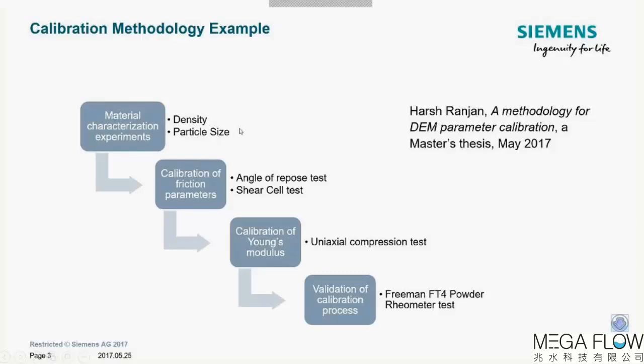We can then do some initial approximations, keeping in mind that we want to simulate the particular flow regime and particular number of particles in a reasonable time. So we don't want it to take too long. So there would be some approximation on the size of the particles and the stiffness of the particles set at this point.